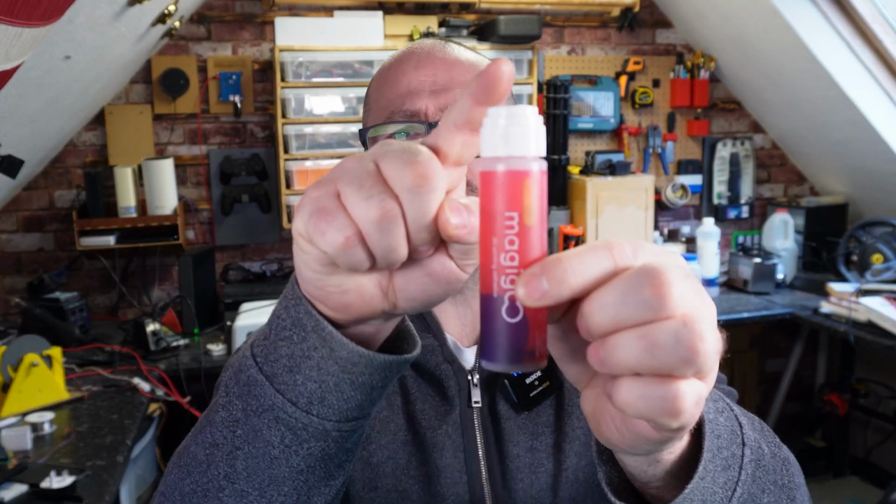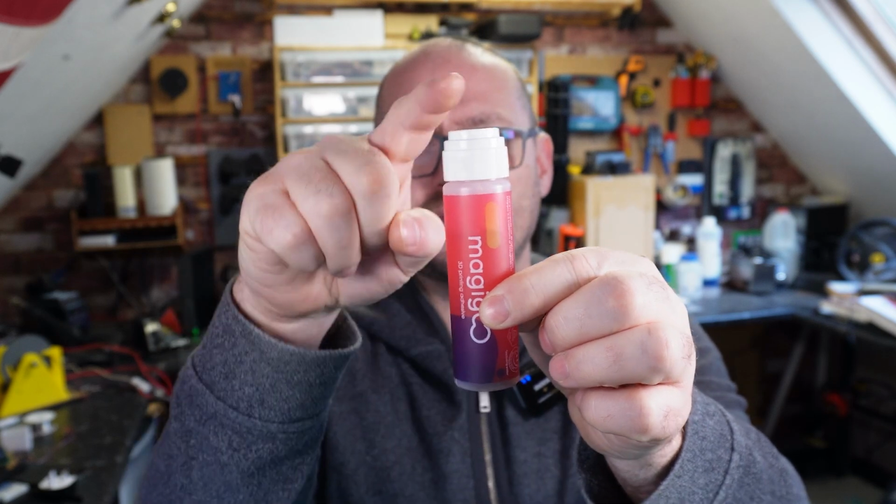So what I'm going to do is roughly trace out the shape of our bottle, and we're then going to apply some constraints to it to pull it into some accuracy, and then we're going to turn it into a 3D model of this bottle using one sketch and one operation. The fewer operations that you can use to achieve your end goal, the better. For a simple project with just one item, it's not too much of a problem to have lots of different operations to get there. When you get into a complex project, your timeline, certainly in Fusion 360, can get incredibly long.